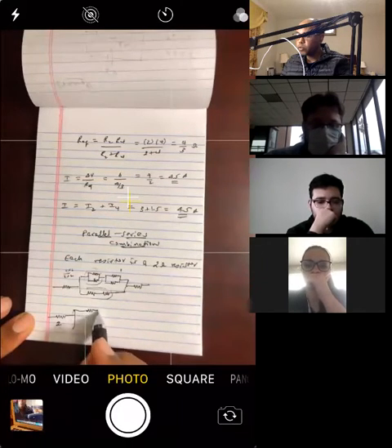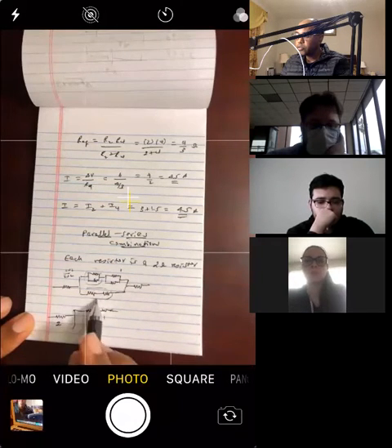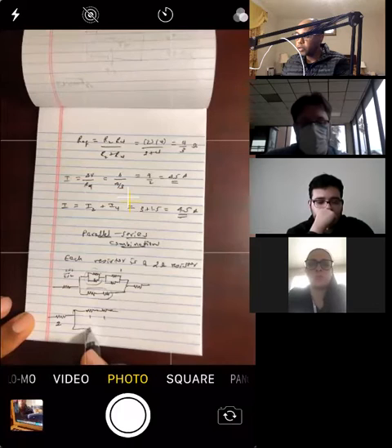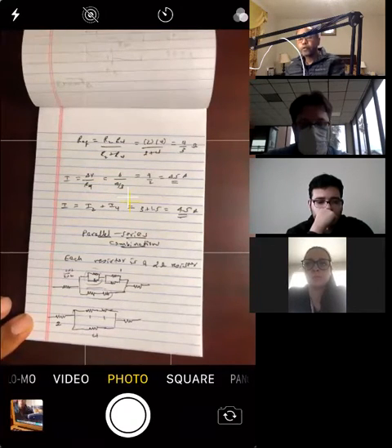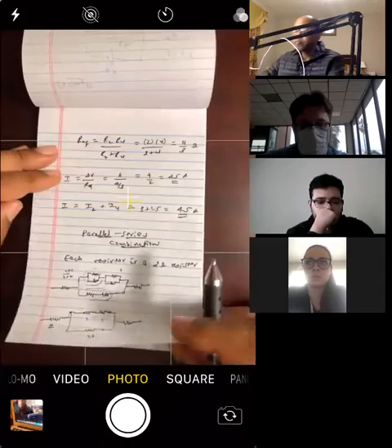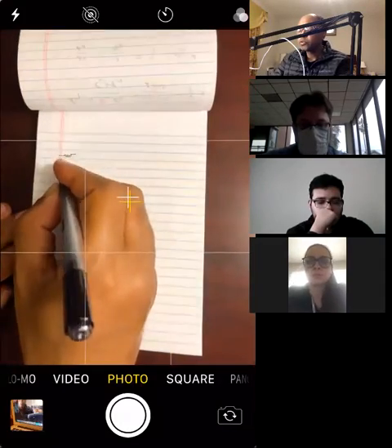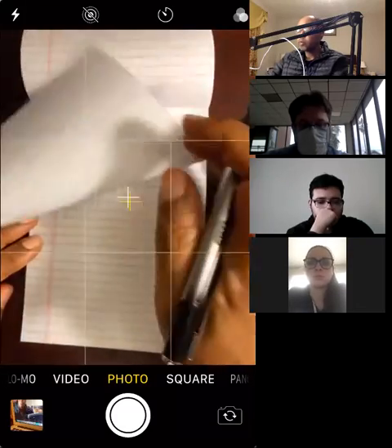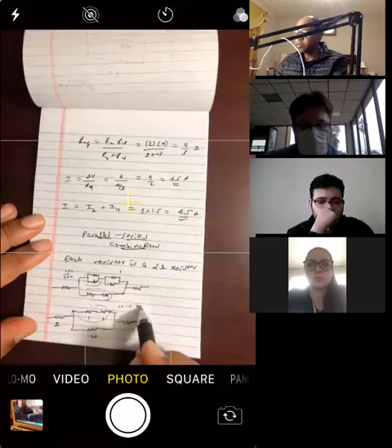The equivalent resistance is 1. It's also 1. Okay? And then these are in series, 2 plus 2, that's 4, right? So I've got 4 over here. And then I got another 2 over here. All right. Next, what can I do? I can add these two. Okay, they're in series, right? I can further simplify it. So I have the following. I have this 2, okay? And then I combine these two. They're in series. I simply add them. It's 1 plus 1 equals 2.